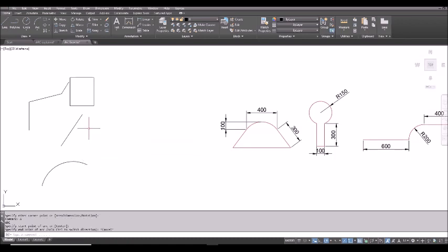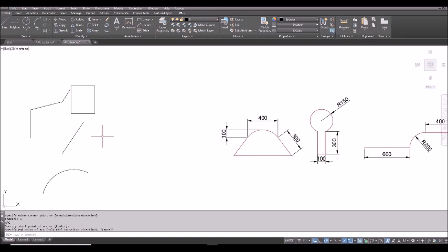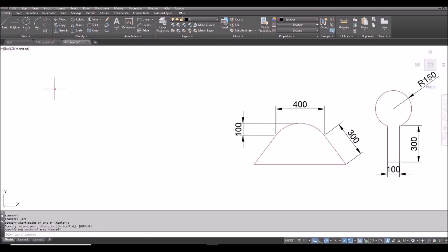Okay, and for your reference, the opposite is also correct. What I mean is, for example, you draw an arc first, and then now you type the line command L and spacebar twice, 1, 2. You can see the line will continue from the endpoint and tangent to that arc. Okay, so now we can do this exercise.